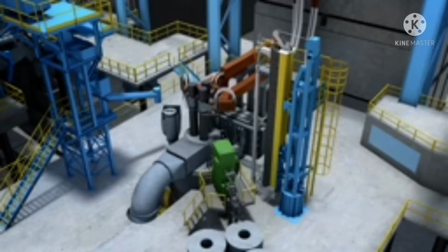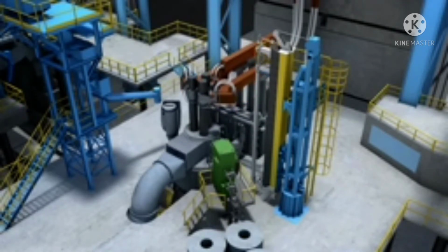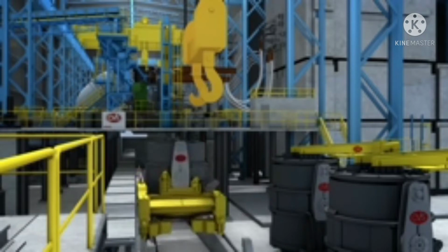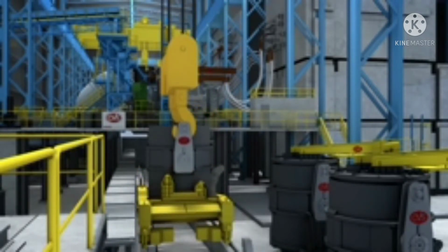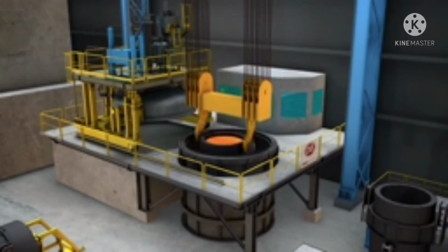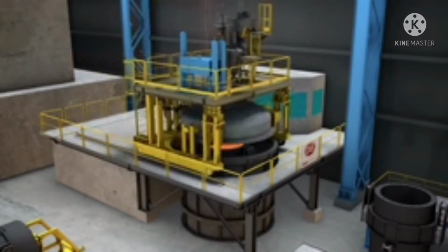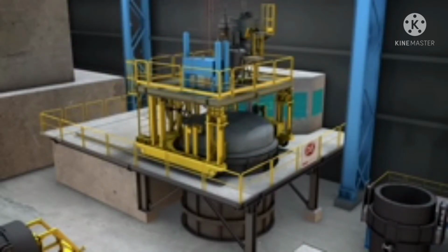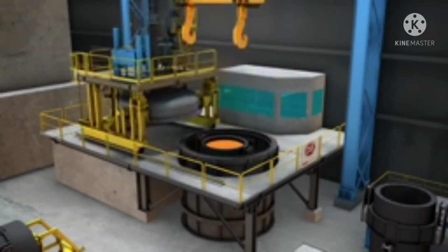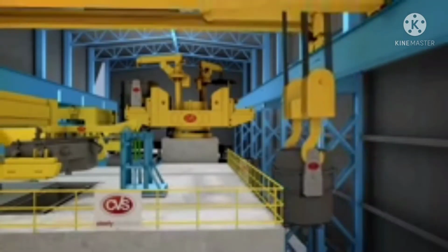Next, the newly formed molten steel needs to be adjusted to make the perfect steel composition. This is done by either manipulating the temperature and/or removing certain elements. This may include processes such as degassing, stirring, ladle injection, or argon bubbling. Now, we have the bones of our steel.